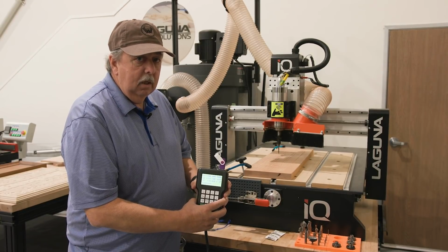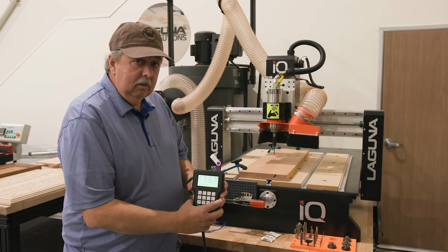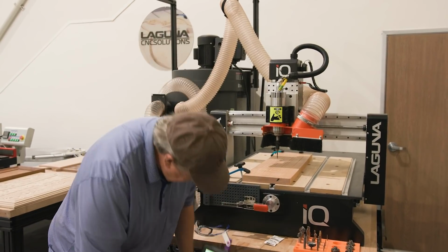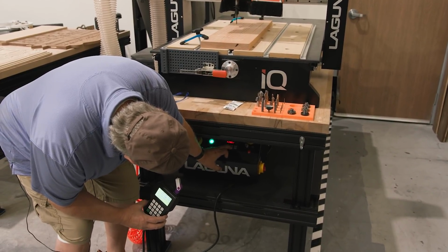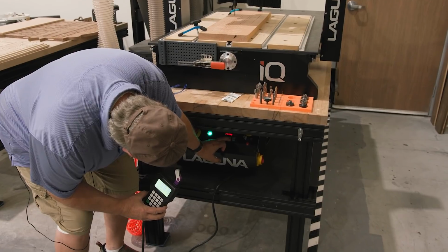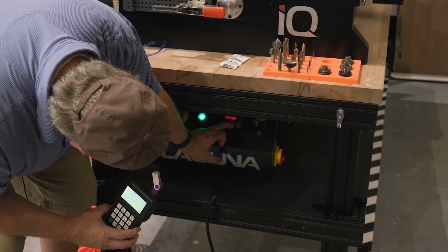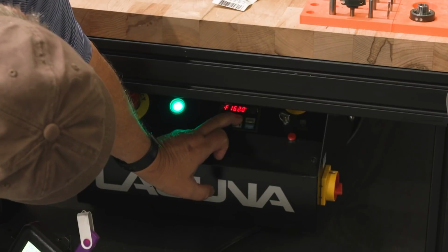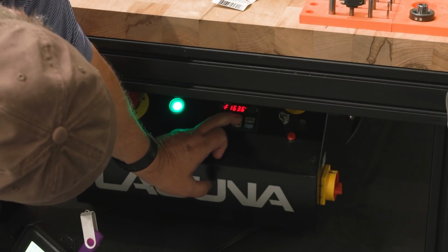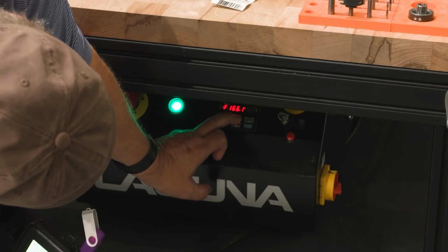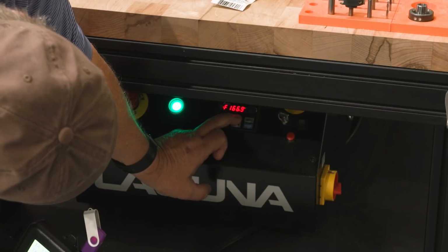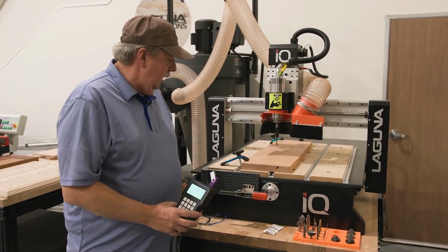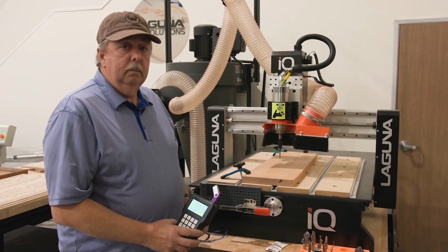We know that by taking 10,000 and dividing it by 60. That's how you decide what the 10,000 RPM is. 10,000 divided by 60. So by pressing the button, we're now at 167. I just rounded it up. So the speed should be right. We'll watch it and see how it cuts. And if we need to adjust it up or down, we will.